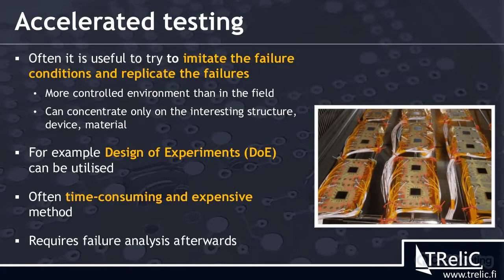directly to accelerated testing, just mentioning that it is also a tool for failure analysis. And sometimes you need to repeat the conditions which caused the failure. So then we use accelerated testing, and this can be extremely beneficial to really check why the failures happened. And we can use some supporting techniques like design of experiments to make it an even more powerful tool. But of course, this is time consuming and expensive. But when you really need to find out what's going on, we quite often need to do this also to support our failure analysis.